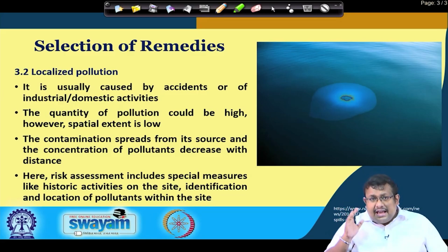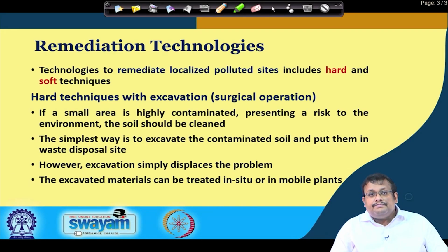So, the remedial measures which you have to take for controlling localized pollution are different from those for diffuse pollution. Now, technologies to remediate localized pollution sites basically include hard and soft techniques. We will discuss both hard and soft techniques now. Hard techniques include excavation, also known as surgical operation.